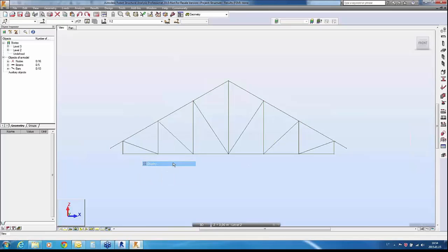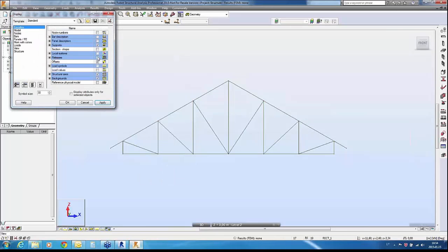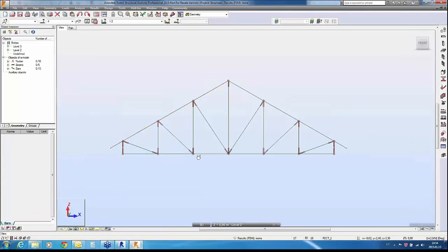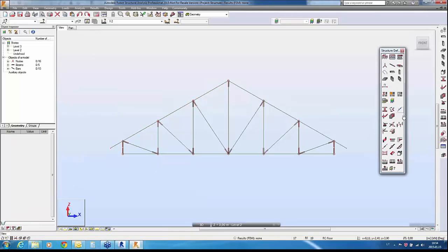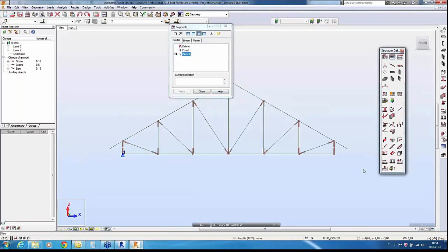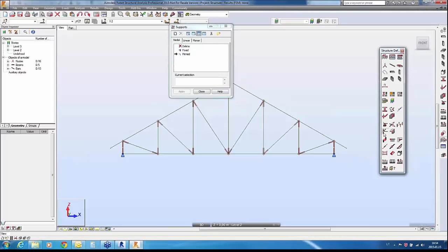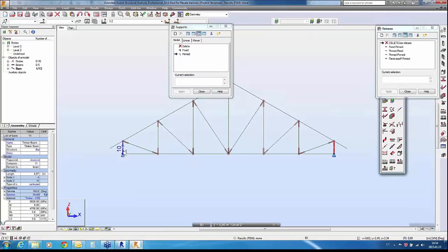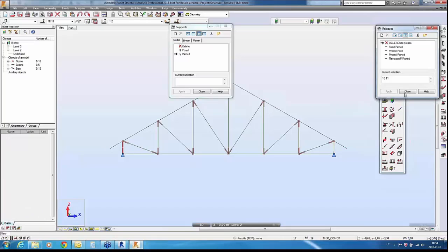I can see that elements has releases. Type of elements is the same as in Revit, and it has material properties for structural analysis. We can just go on further, like to add some supports here, or maybe to remove some releases if we think that it's not necessary.